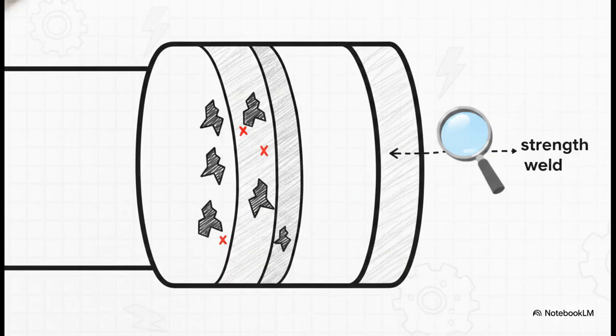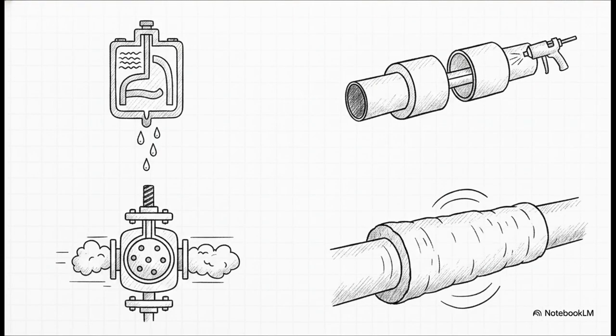Of course, connecting all these pipes safely through fusion is where the real structural integrity comes in. Because you can have the strongest steel in the world, but if your joints are weak, the whole system fails. When welders tackle thick pressure vessels, they use a multi-pass technique. But there's a major enemy here: inclusions. These are basically pieces of foreign solid matter that get accidentally trapped inside the weld. A perfect multi-pass weld has to fully penetrate and fuse with the parent metal without leaving any of those dangerous inclusions behind. That's how you get a strength weld that's just as tough as the original pipe. Now this skeleton is packed with some highly specialized gear. Steam traps, for instance, let liquid condensate drop out while keeping the valuable steam locked inside.